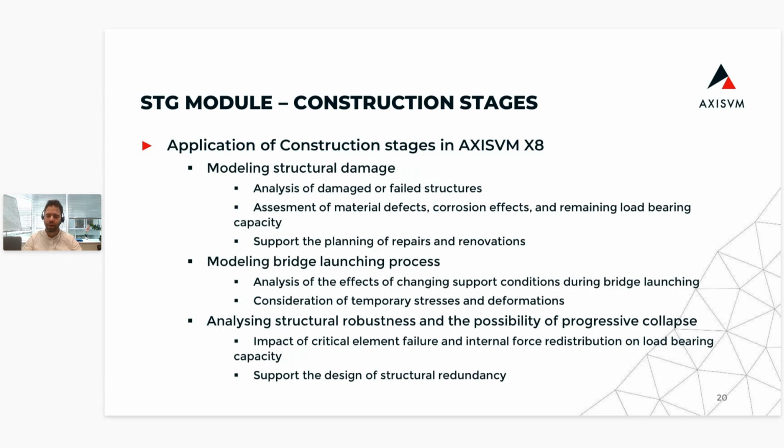We can use the construction stages in situations where the support conditions are changing during the construction process. So bridge launching process is one example. And we can also analyze structural robustness or support the analysis of structural robustness and the possibility of progressive collapse.